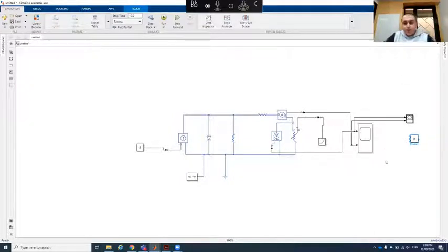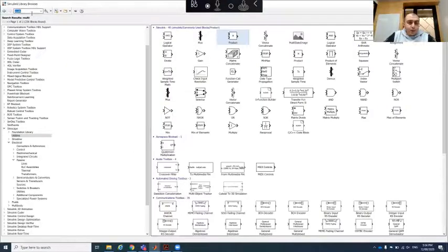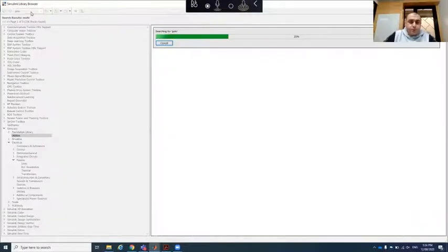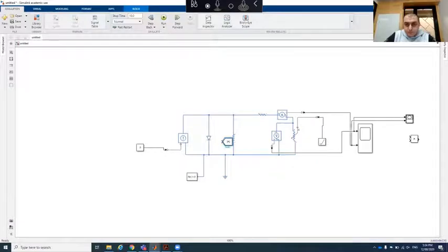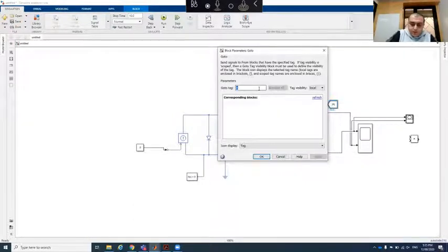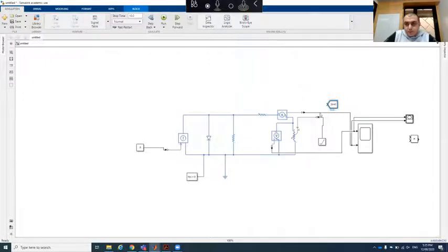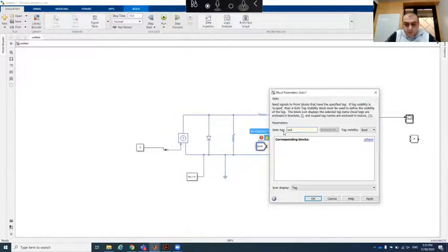Okay, if you see here, connecting all this wire will be a headache, so I can use a label. Just type O2. Okay, so I can use this label to simplify my circuit. This will be the output current, so I can delete all this. Copy. And I need V out as well.